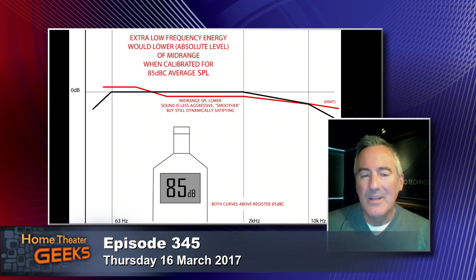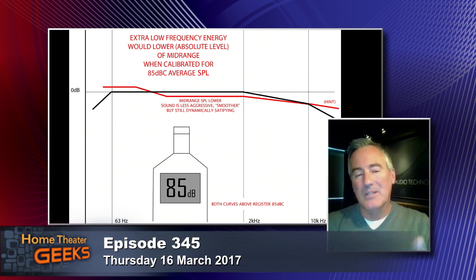As long as you're not making a bump, but you're just kind of smoothly increasing the energy, it will also serve to kind of soften up the sound. You can't have a peak in there, but if you have a bit more top end, it will soften up the sound too. And so our speakers would tend to follow that red line. And most listeners that come through here, one of the comments they make is, wow, that was crazy loud, but not at all sort of harsh or fatiguing. It's able to be loud without seeming overly loud or obnoxious like the X curve provides. So that's my 2 cents.